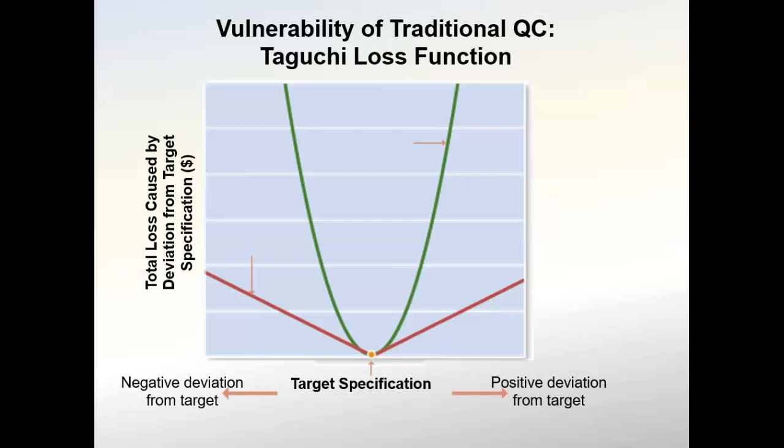An inspection-intensive program also brings up the issue of tolerance, or setting the boundaries on permissible variation. Tolerances are at least partially determined by the cost of nonconformance, which is traditionally assumed to be a linear function of the degree of nonconformance. So, for example, if the difference between an actual measurement and its specification were found to be twice as large for one unit of product versus the next unit, it would be assumed that the previous unit would cost the organization twice as much as the next unit due to its nonconformance.